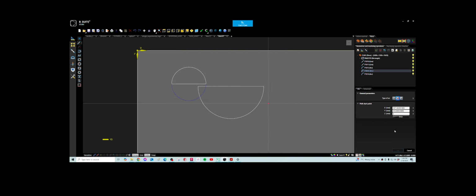So something simple can be very handy. Usually when I'm doing casing, you only have first point, end point, and middle, right? And then the machine will find the radius. This is not every time 100% accurate, because sometimes the radius of those arcs might not be as correct as the machine will do. So it's recommended to have like a template and then double check on the template.